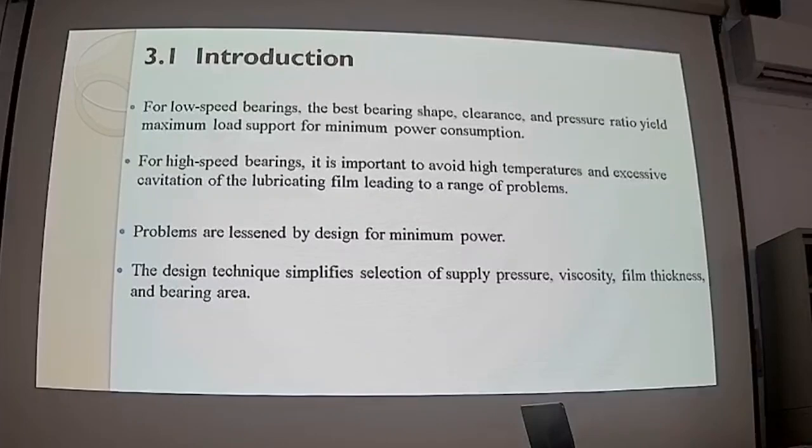It means that sometimes, especially when you have a recessed bearing design, there is a vacuum place lacking lubricant in some specific area of the recess. We call it cavitation. Cavitation 叫做空隙，其实就是对润滑油来讲，那一块缺乏润滑油，只有空气。通常是在高转速的情况下才会有。高转速而且是有腔式的轴承，会有 cavitation。